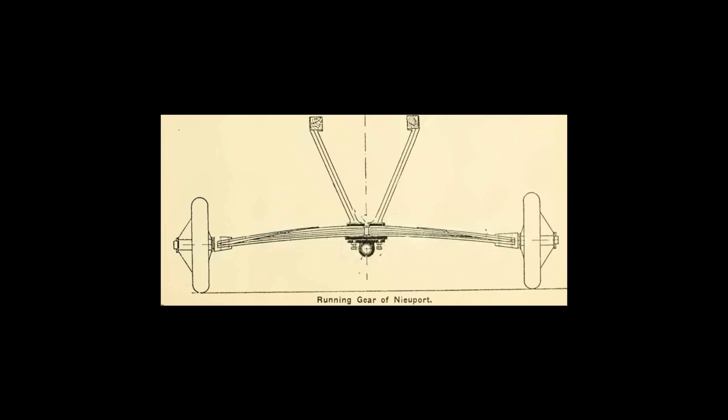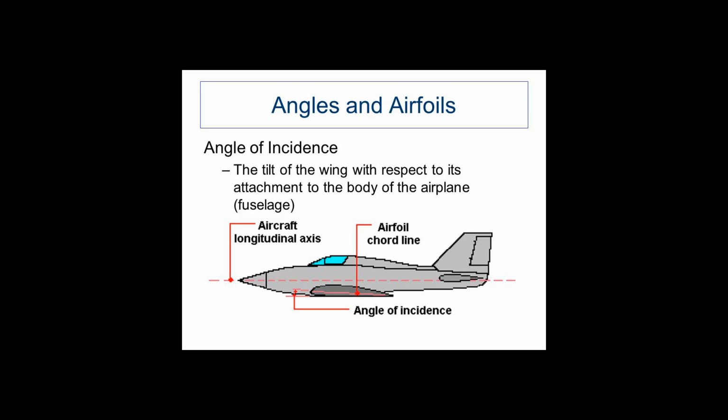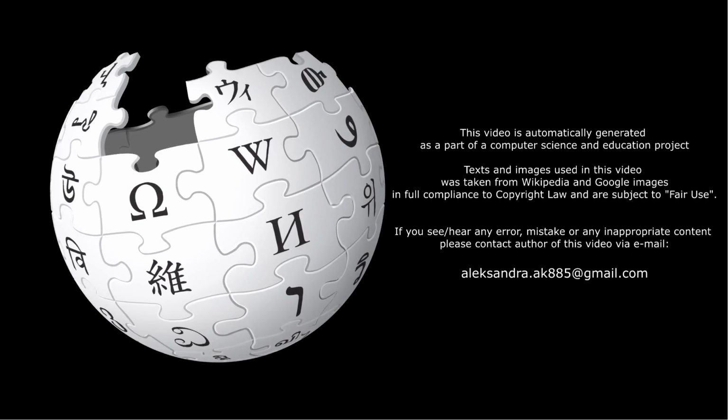Standard mean chord. Standard mean chord, SMC, is defined as wing area divided by wing span. SMC = S/b, where S is the wing area and b is the span of the wing. Thus, the SMC is the chord of a rectangular wing with the same area and span as those of the given wing. This is a purely geometric figure and is rarely used in aerodynamics.